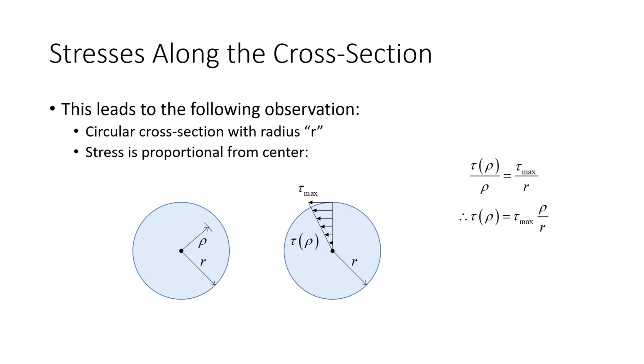So for example, if I have a beam that's subjected to, let's say, a uniformly distributed load. Y'all remember how to draw moment diagrams? Or y'all remember that from statics? So I can determine where that maximum moment is. Let's say it's in the middle. Okay. But where is the maximum stress from that moment? Well, it's either on the top or the bottom of the beam. How did you figure that out? We'll talk about that later. Don't worry. Well, likewise with torsion, where is the maximum stress from torsion? On the outer ring.